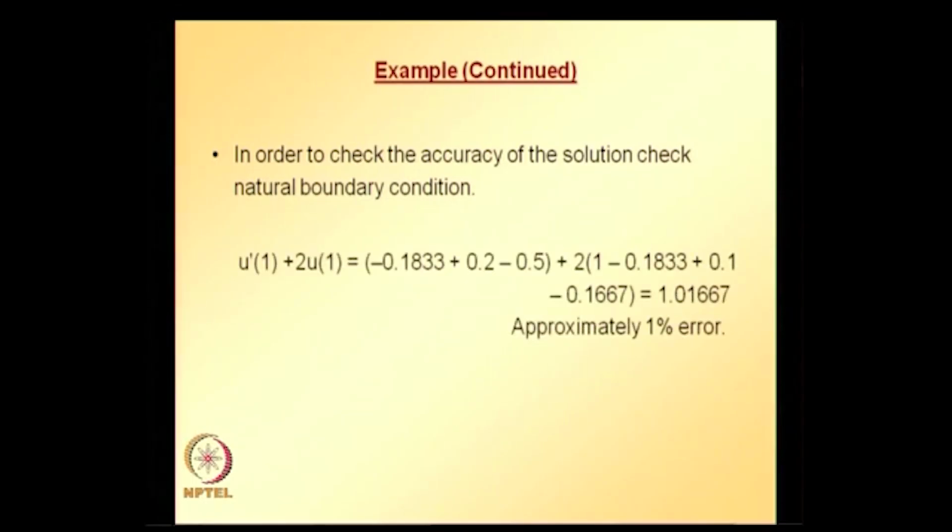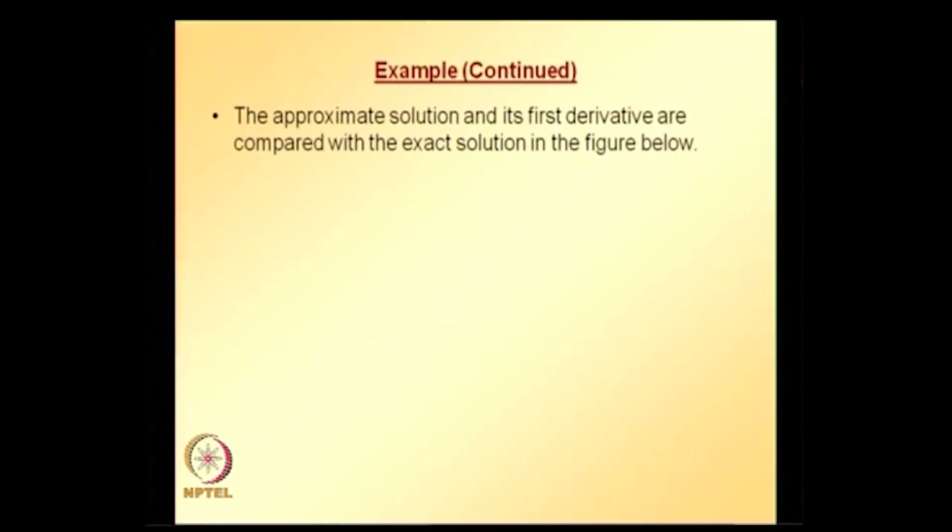You can see, as expected, the cubic trial solution results in less error. With the quadratic trial solution you have 10% error, whereas with the cubic trial solution the error became 1%. You can further follow the same steps to do higher order trial solution approximations also.